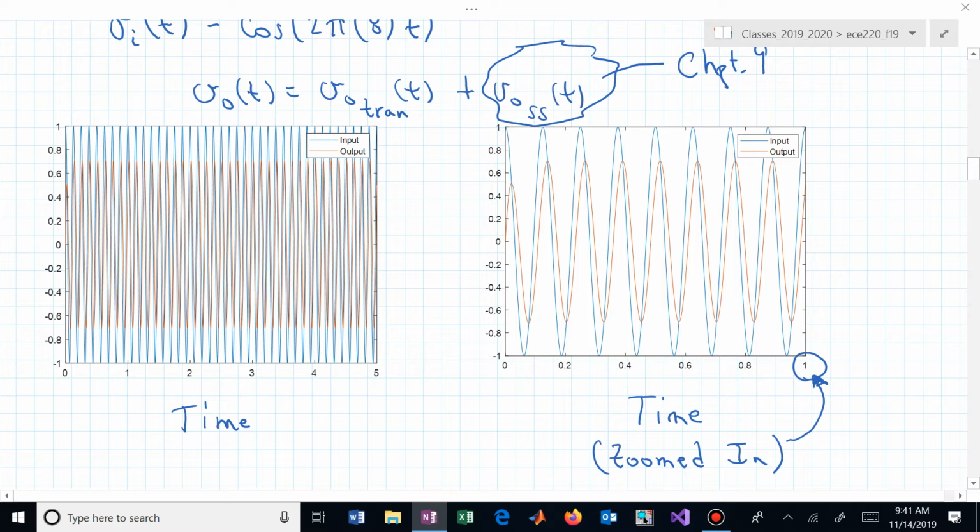In this particular case, hopefully you can see that we have a transient interval where that red, because what happens? We have an unenergized system, the capacitor is just sitting there, and then all of a sudden we hit it with 1 in terms of our cosine's peak. Is that what I put in? A 1. And then it starts oscillating as a sine wave, as a cosine wave. Well, it takes a while for that capacitor to sort of get in sync with the sinusoidal input. And this short interval is the transient interval.